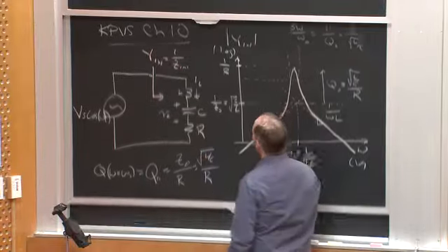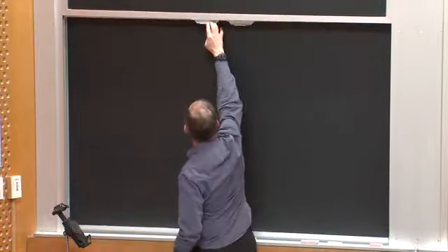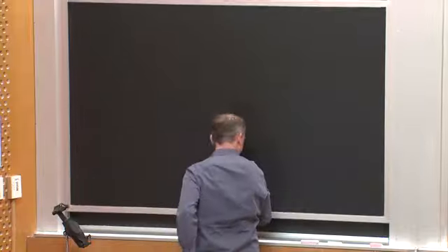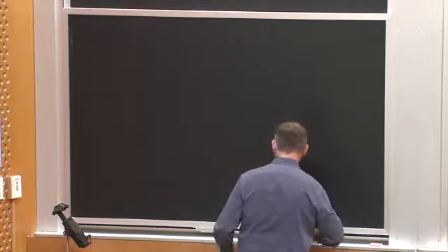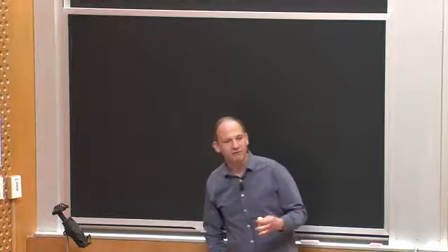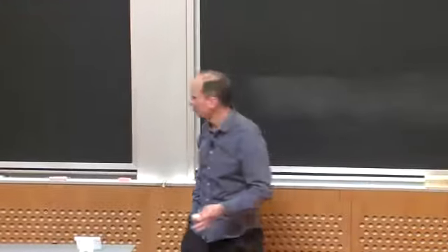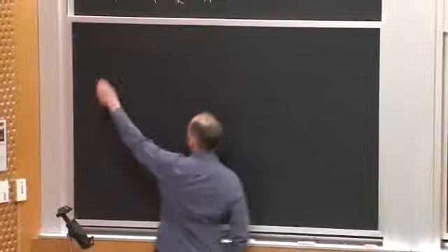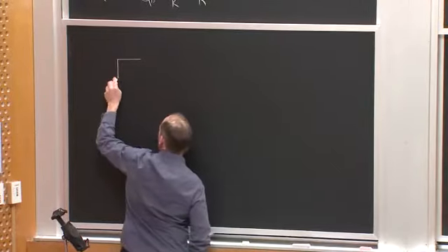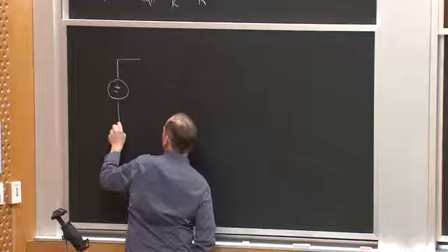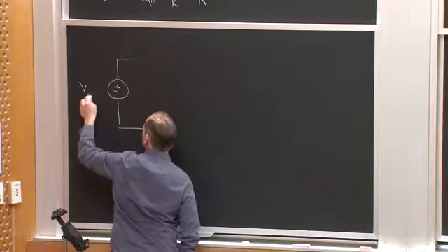Okay, so maybe what I would do, and this could either be called a half-bridge inverter, resonant inverter, series resonant inverter. Somebody in the RF field might call it a Class D power amplifier. That's another term that gets used. But it could look like this. Maybe I'll have some voltage VDC.